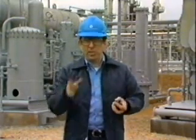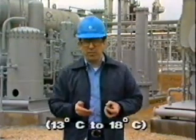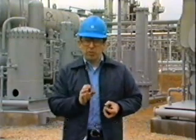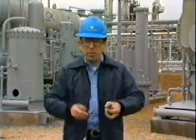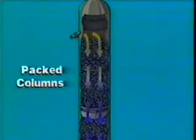Four feet of packing is usually standard and sufficient to achieve dew point depressions up to 55 to 65 degrees Fahrenheit. If higher dew point depressions are needed, additional packing may be required. Packed columns utilize the same process as tray columns, where liquid glycol flows down over the packing and the gas flows up through the packing. Packed columns are less expensive. However, they tend to channel and have poor flow distribution.